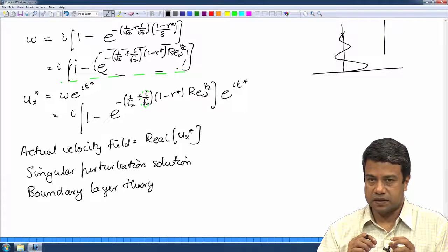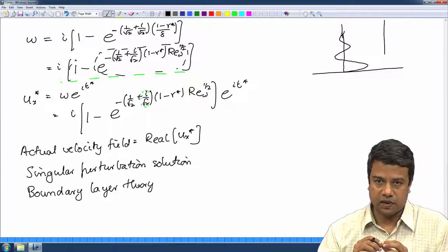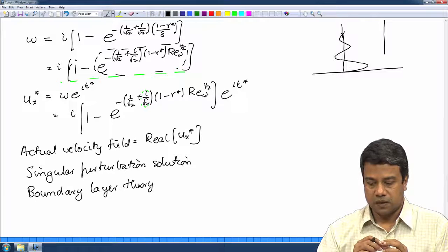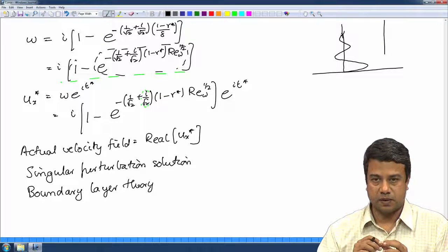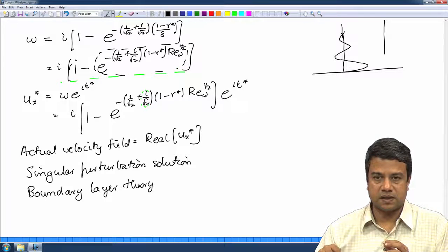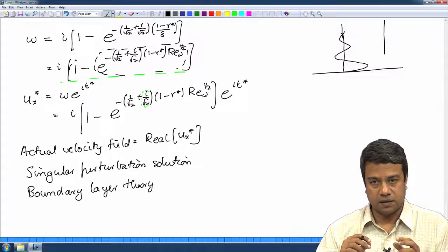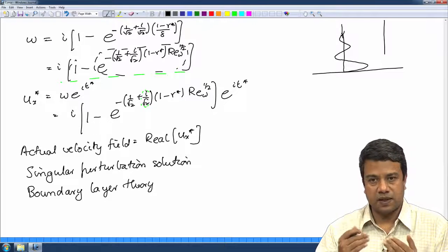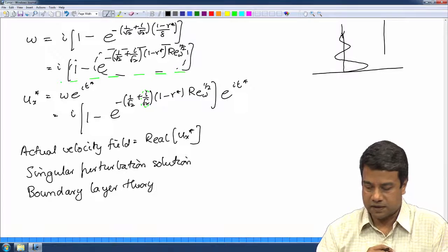And the thickness of that region is determined from the condition that inertial and viscous forces continue to be of equal magnitude within that thin region, even in the limit as the Reynolds number goes to infinity or the Peclet number goes to infinity. The boundary layer thickness delta will be some power of the Reynolds number or the Peclet number. It will not in general be minus half as in this case, it could be a different power. But once I scale it that way, within this region the inertial and viscous effects are of equal magnitude, and therefore I can solve the boundary conditions, and from that calculate the flux at the surface, by taking the derivatives of the temperature field or the concentration field.